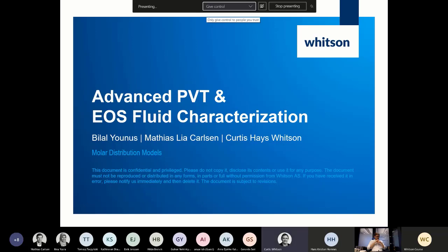But basically, through all this regression, he'd been able to tweak all of the TC, PC, acentric factor, all these properties into aromatic-like properties. When he came back from lunch, I said, well, I think I understand why you had to change the properties so much, and I showed him the Watson characterization factor calculations and so forth. I said, well, let's just do an experiment real quick.